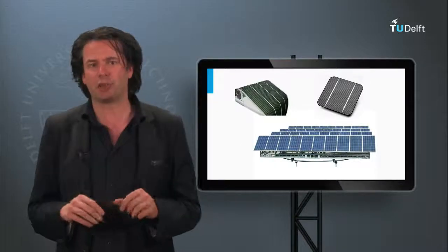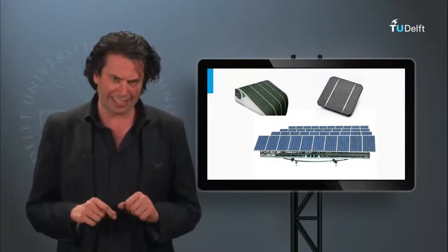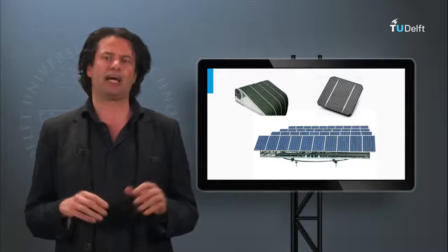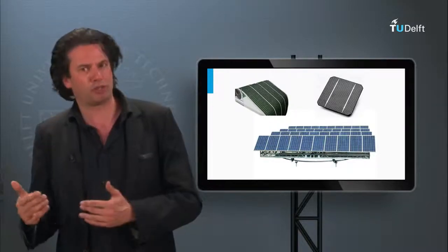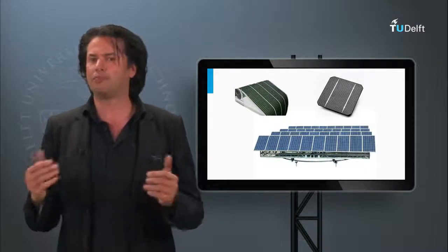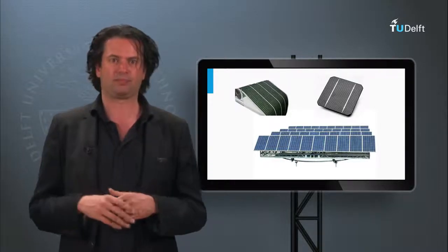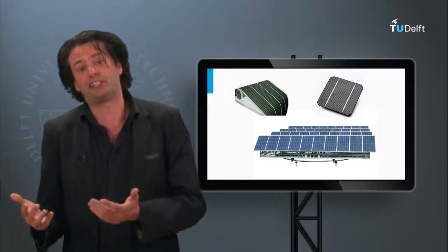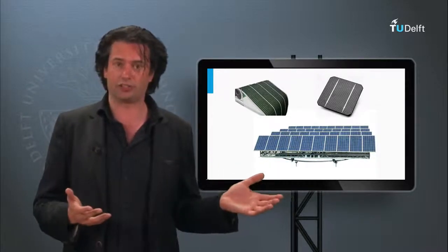More PV technologies are being analyzed at the Delft University to understand the extent of the temperature effects. As said before, the amorphous silicon technology shows very low temperature coefficients due to its high open circuit voltage. This means they would show a better response under high temperatures. However, their efficiencies are far lower compared to some of the best crystalline silicon technologies.